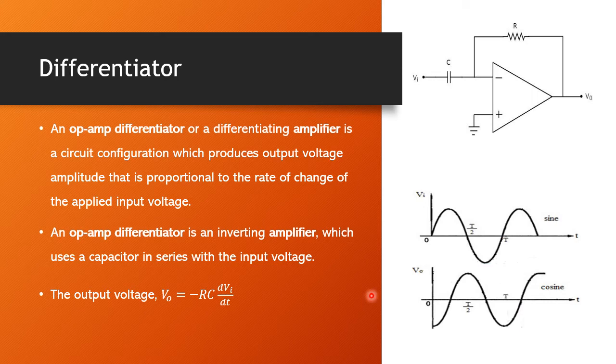The differentiator is also an inverting amplifier, since we are connecting to the inverting terminal, and it uses a capacitor in series with the input voltage. Here the output voltage amplitude is proportional to the rate of change of the input voltage, that is the differentiator.